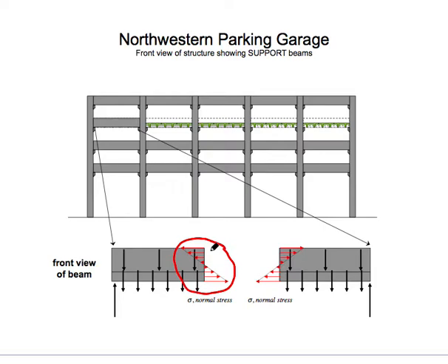And recall that for the hypotheses that you had on how the stress distributions were in the beams, there's a linear distribution of the normal stress throughout the thickness of the beam. There are also shear stresses developed. These are the shear stresses that are the resultants of the shear force V. And what you might recall is that these are not linear distributions, but for a rectangular cross section they're parabolic.